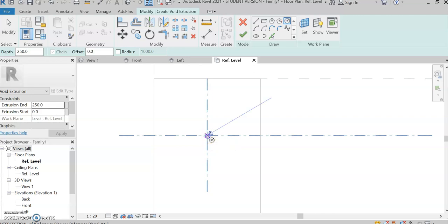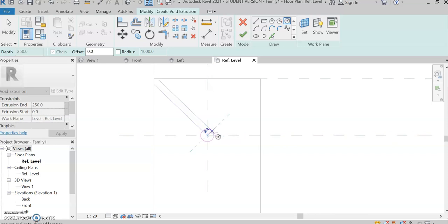6mm diameter, that means it's 3mm radius. So if I did 3mm radius, it's going to be a perfect fit. I want it to be quite tight, so I'm going to nip that down by a little bit. I'm going to make it 2.65 radius.